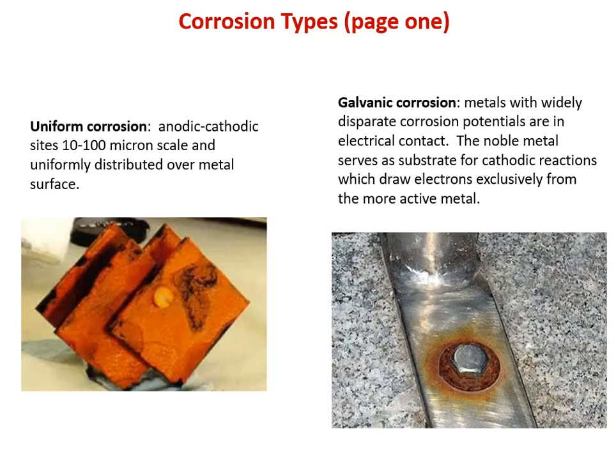So that entire surface of shiny stainless steel is drawing electrons from that poor corroding washer and releasing it to oxygen reduction as a cathode reaction. So the current density at that washer is very, very high, and as a result it's losing metal atoms and forming corrosion products and going away very quickly.